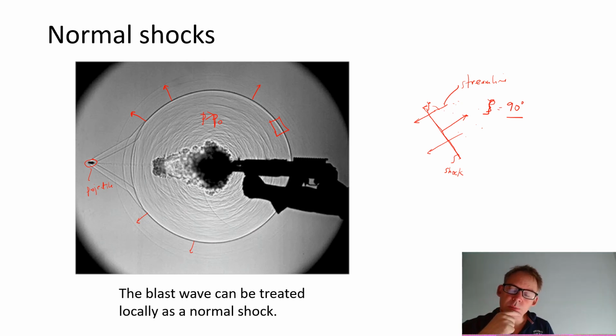It's a bit worse than that, because once it's reflected, there's an amplification of the pressure close to rigid surfaces, which means that they have a great potential for enhancing damage. The overpressure required for breaking things like windows is very, very small. You only need an overpressure of 5 kPa, and that's sufficient to blow out windows easily.